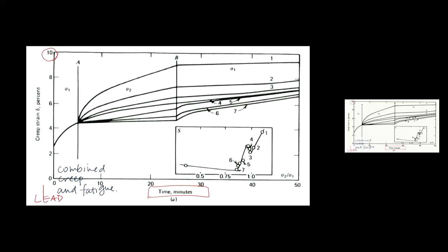And so we have a first curve here. At 0 minutes, a stress is applied to the sample, and the strain is recorded. That's not really a creep strain at that point. It's an instantaneous strain, and it's already almost 3%. So it's quite a high stress. We're going to call that stress level 1, sigma 1. All samples have the same sigma 1 over 5 minutes. There will be some creep during that time, right? Even higher than 1%, because sigma 1 is probably fairly high.